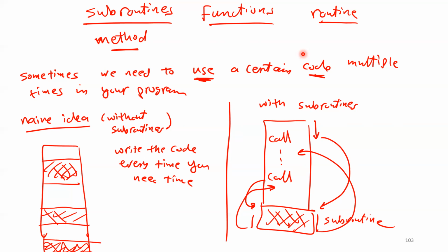What you need to worry about is how can you use stack? As I told you before, I give you several examples. As I told you before, I want to use the register X, but I need this value back. Okay. So I'm going to push it in the stack. I'm going to use register X, register A, Y, whatever, and then I'm going to get it back. That's it. Push and then pull. That's the easy way to use it.